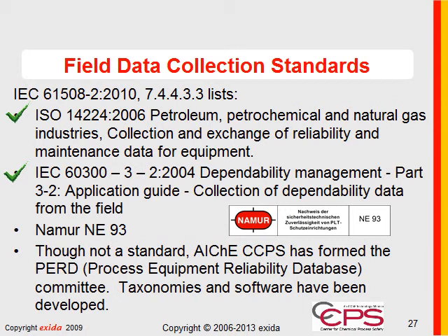Another question came up. Thank you so much for all the questions. Does the data have to be from a specific end user or from the collective experience of a manufacturer? Well, the fact is the standard does not say. As a reliability engineer for the last 25 years, it's my interpretation that any data that is valid from field operation in a similar environment and in a similar application can be collectively gathered and used. And that's exactly what we do at exida. I'm going to tell you about it.